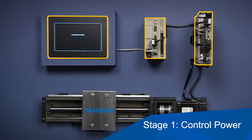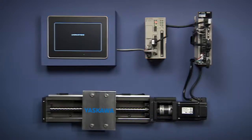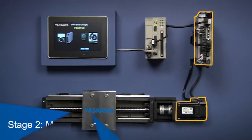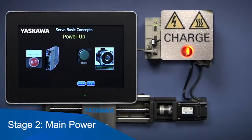The system is typically wired to power up the controller and the operator interface at the same time servo control power is established. The second stage is to apply the high voltage and high current power source that the amplifier will use to drive the motor. We refer to this as main power. The main power input allows flexibility in wiring to the servo amplifier.